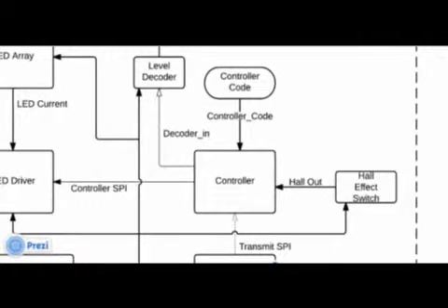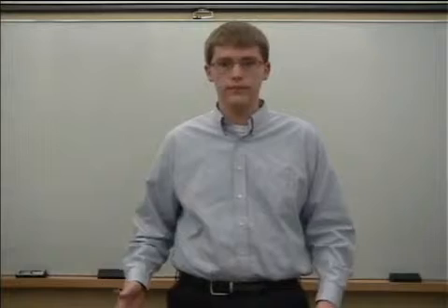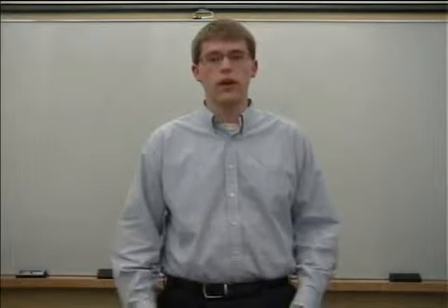The controller will need to perform 2 main tasks. First, whenever a signal is sent through Zigbee, the controller needs to determine if that signal was meant for that particular LED cube. And if it was, what does that signal mean? The second task the controller needs to perform is controlling which LEDs are to be lit and when. The controller cannot directly power the LEDs though, so it will have to send a signal out to the LED drivers through SPI, the serial port interface, also pronounced SPI.